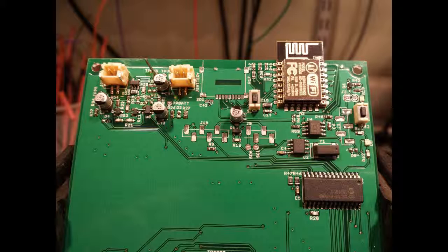I ended up taking those connectors off because they are really difficult to pull the mating part out. It's good for the final product because it won't fall apart in shipping or vibrate loose, but for debugging, it's really difficult to get those connectors apart. Those are JST connectors, so I went in and pulled those off the board, and I just soldered some wires right onto it. The SD card slot itself, I can't get the part for that, so I'll have to change the footprint on that as well.